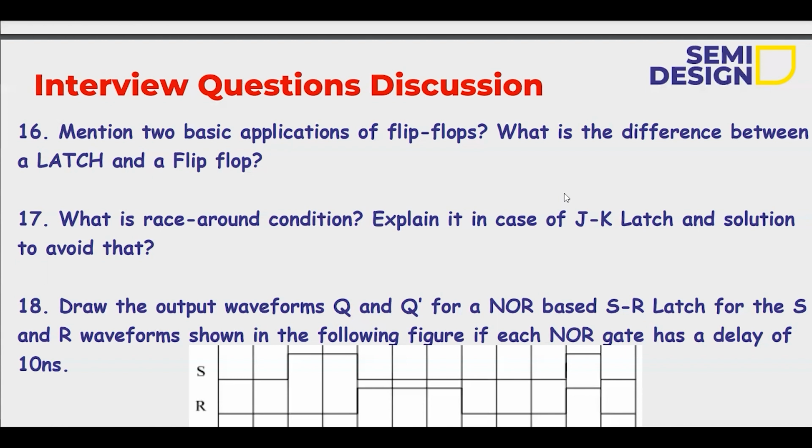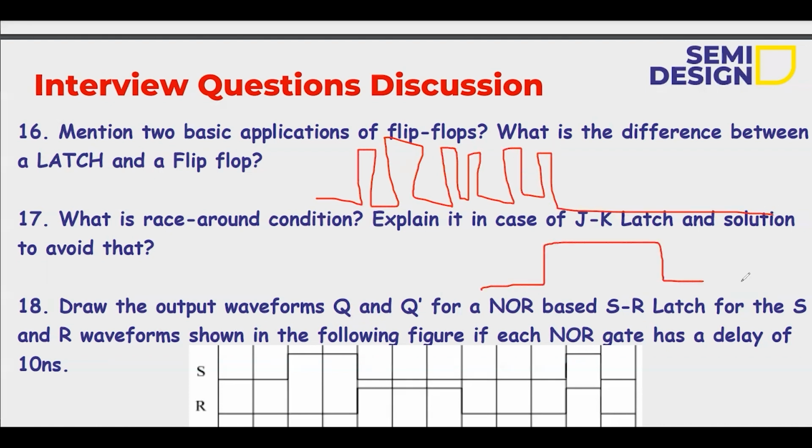And the difference between flip-flop and latch is that a latch is level sensitive. Because of level sensitivity, we face many disadvantages, such as glitches at the output side. Glitches mean the output is not in a constant state, moving like 0 1 0 1, when it should be constant for a certain time. Due to level triggering, the output doesn't have controllability on the inputs, so we face glitches at the output of latches.